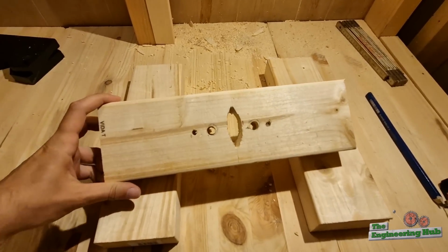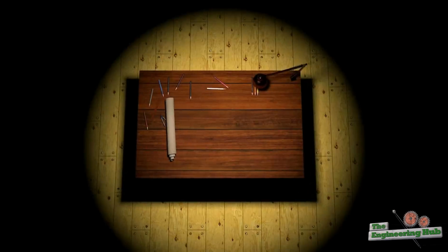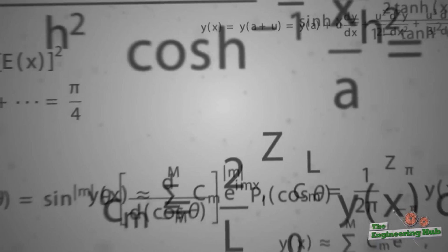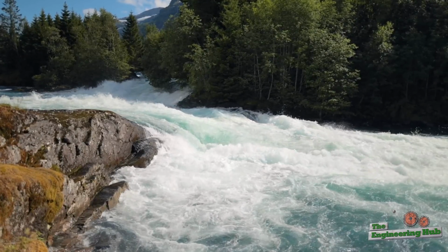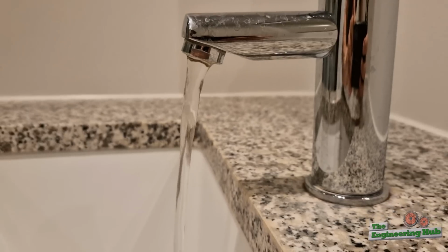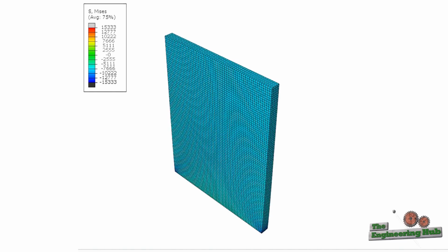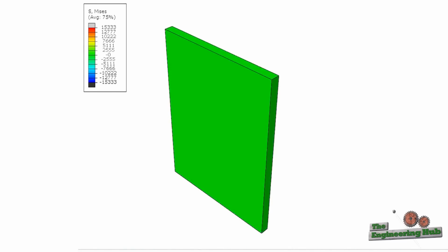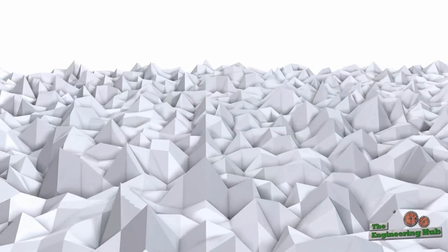Before I show you the experiment, let's step back and give some theoretical background. Instead of going deep into technicalities, we can reason in terms of the flow analogy. This compares the stress state with an equivalent fluid flow state. The basis for this method is the fact that solids and ideal fluids comprise a continuum that for special cases can be expressed in terms of a potential function governed by a variant of the Laplace equation.